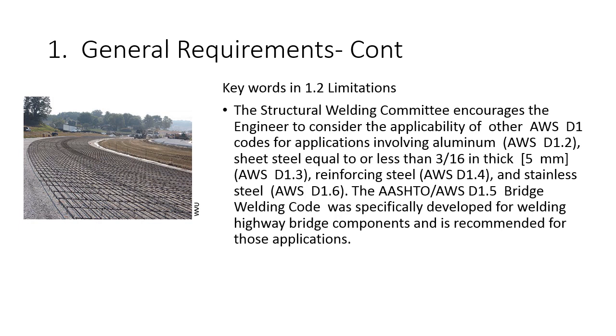AWS D1.1 is not the all-encompassing welding code. I've dealt with mechanical engineers in the past that thought, well, it's the welding code. Weld it. Like it's an all-encompassing code that covers everything from welding a broken heart to the crack of dawn. No, this does not cover that. It is strictly for structures, buildings. It's not for driving cars across or anything that's road-based or with rebar. No, this is a structural steel welding code. And as an engineer, you need to understand that, or a designer, or anybody dealing with this code.